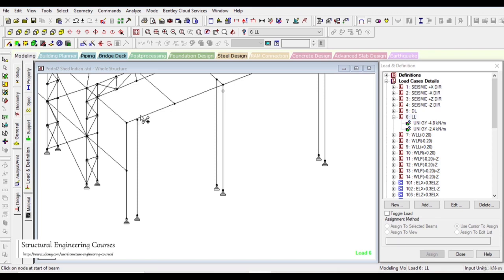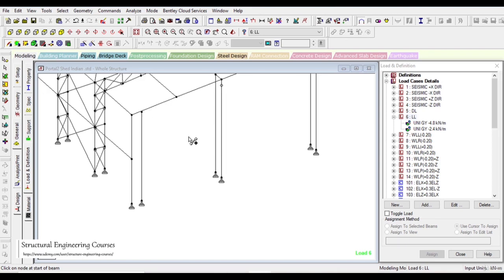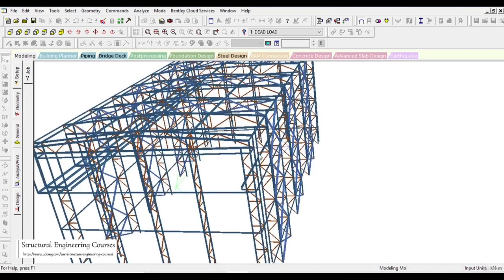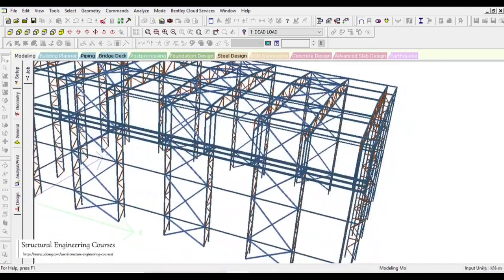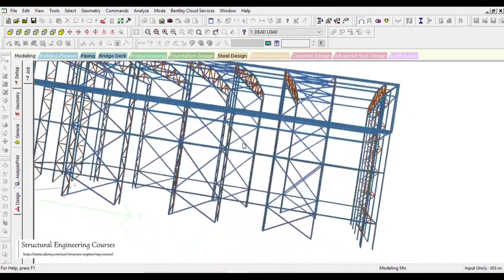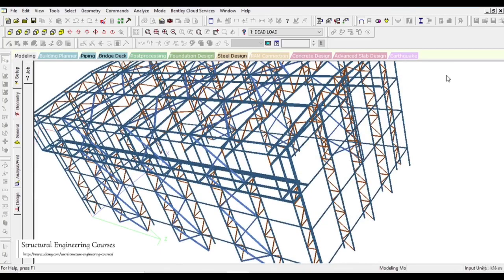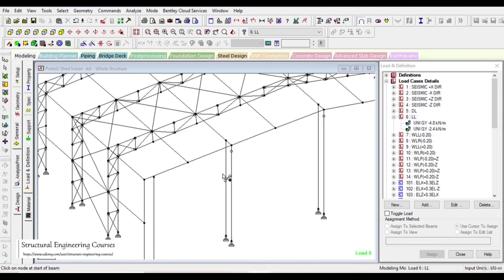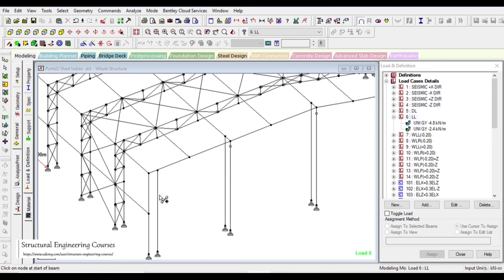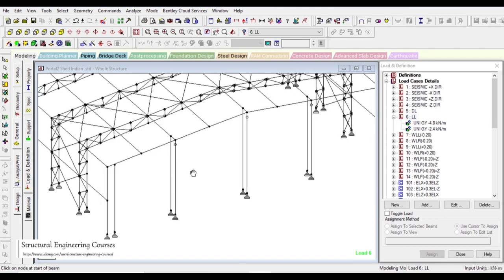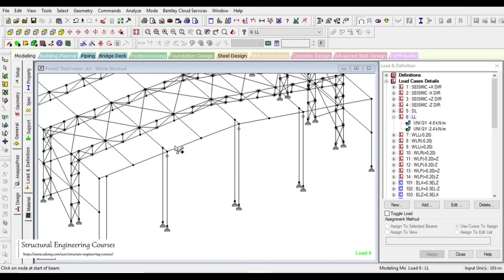Here you can see that this member is not matching with this beam here. Plus as an additional exercise, what you really need to do is that you need to copy this member along the vertical axis also. So you can refer to this typical arrangement here also, that what exactly he has done. He has drawn a 3-dimensional truss system at the ends. What exactly he has done is that he has drawn a 3D truss or space truss on the gable ends, but that is not as much required, as the forces on these members are also very less.